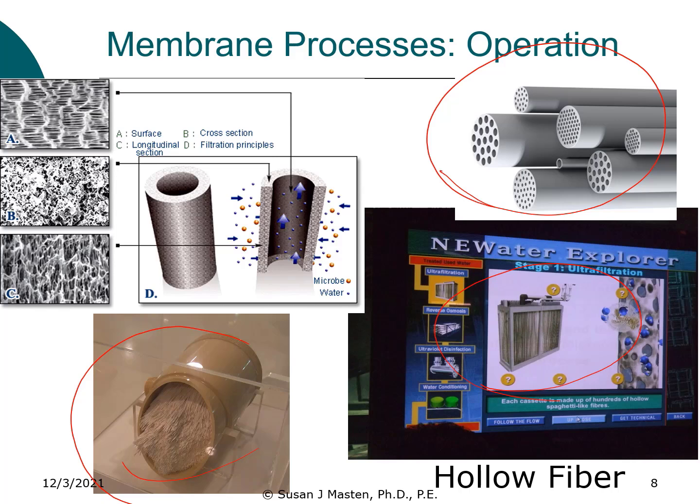The treated water actually flows through the membrane, and these work as an outside-in membrane. So the water flows in from the outside through the tubular membrane and out through the center. Now these ceramic membranes actually operate as inside-out membranes, where the water flows into these tubular membranes and then out through the walls. So again, here we have an outside-in membrane, and here we have an inside-out. It's really in terms of the flow direction in these membranes.